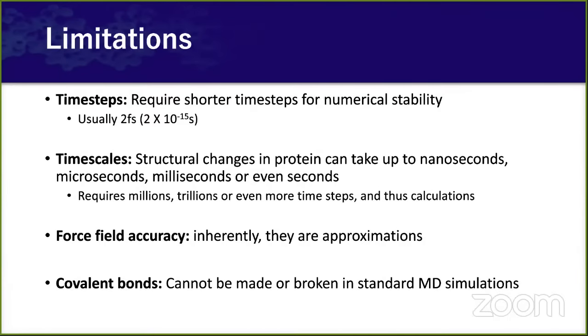When it comes to the limitations, your limitations can come from many sources. First of all, time steps. We will talk about these time steps again when we see the input parameters. Time steps are basically at every how much time frame the calculations are going to be performed by the dynamics engine. Usually these time steps are required at a very, very minute scale to retain the numerical stability of integration algorithms. If you don't use such a small time scale, like at the femtosecond level, the numerical stability will be lost and the integration that is being done will not be proper. So usually we use 2 femtosecond or 1 femtosecond.